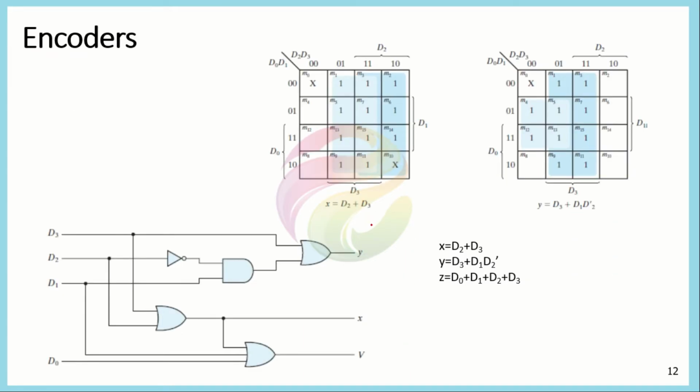Now, if we try to draw a circuit diagram for the outputs X and Y, first we need to design a K map for the circuit. So first we draw the K map for the X here and the Y here. Sorry, this would also be equal to 1 here. For the initial case, when both of them are equal to 0, we would have a don't care term here. For all the rest of the combinations, we just use the method we defined, that for any given x we could consider both values 1 and 0 and form all the minterms.